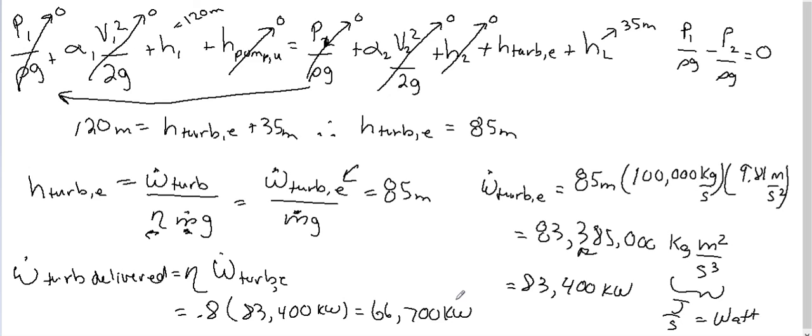That's how you can solve a question that involves the energy equation where the Bernoulli equation won't be able to be applied due to power being delivered to or taken from the system and different head losses as a result of friction.